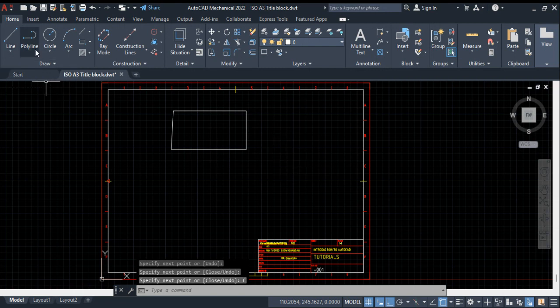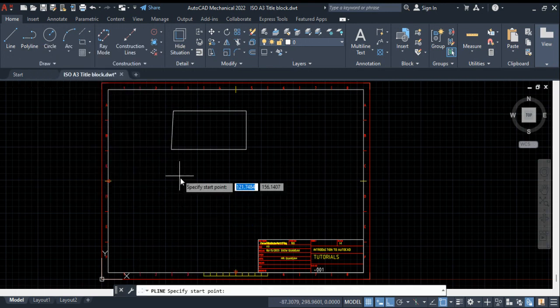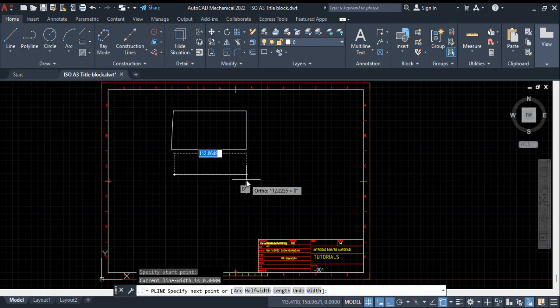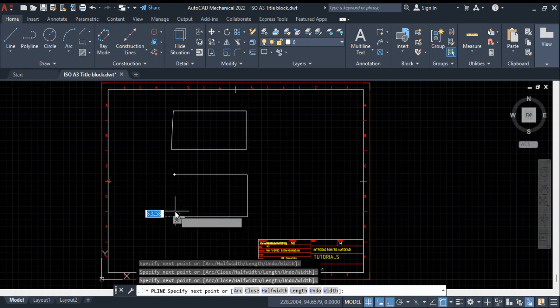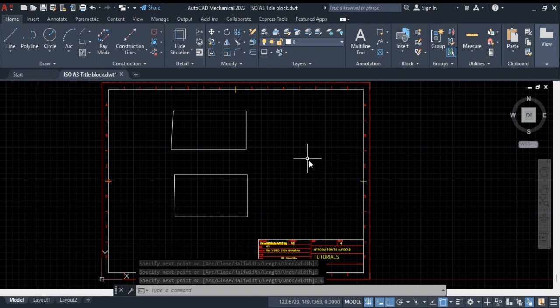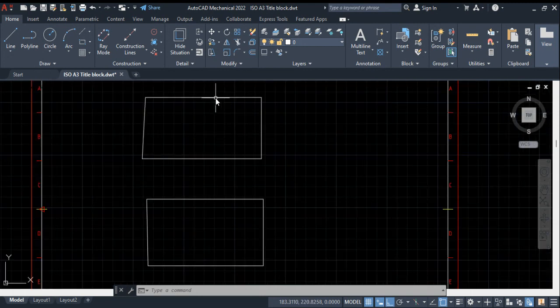All right, then let's now draw a box again, but this time around using the polyline. So I select polyline, I do the same process, click, click, click, and then close, and let's see the difference. So I bring my cursor and I hover it here. If I hover it here, you realize that this line glows. That means that this line is different from this line. It's slightly different. It's just that they are connected, but they are kind of separated.